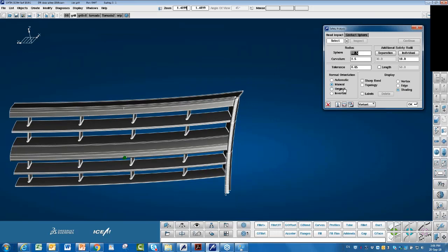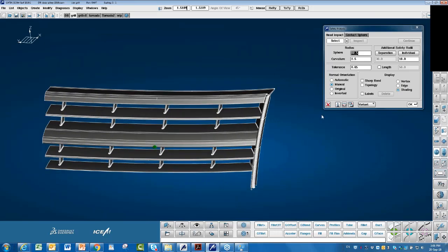I'm going to use a manual mode. We found this is typically the best mode for the first pass, and we can choose a tolerance or an accuracy. This is based on tessellation. This is a little loose, I'll be honest with you, but for the demonstration, I want it to be fast. But typically you might use a finer tessellation than 0.05.